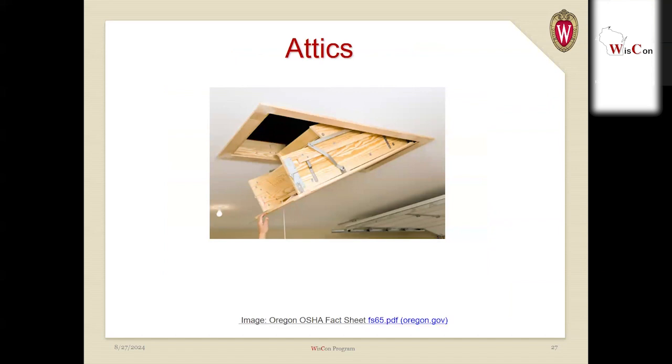Also, attics. Attics are technically a confined space, but they tend not to be a permit required confined space. However, if it's a large attic and there's other crews working in there, and perhaps someone's spraying a chemical, or that it's the summertime and it's extremely hot, there could be some other conditions of that attic space that may turn it into a permit required confined space.